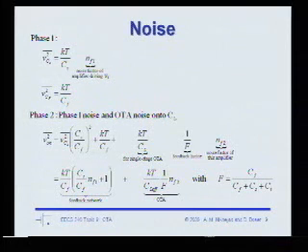So here also, it assumes that the bandwidth of the circuit is mainly determined by CL for phase 2. That's true, right? That's actually a very good approximation. All these amplifiers, we'll see when we design these more and more, that in fact CL is the dominant pole of the circuit. Okay, good, very good question. All right.